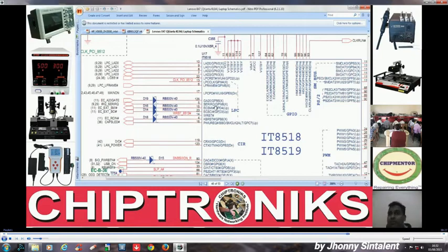Earlier there used to be two pins on the IO controller, one is IRQ2 and another is IRQ12. The IRQ2 interrupt is generated by the IO controller when you press the keyboard, and the IRQ12 interrupt is generated by the IO controller when we touch the touchpad. But nowadays this is combined into one, serial IRQ.